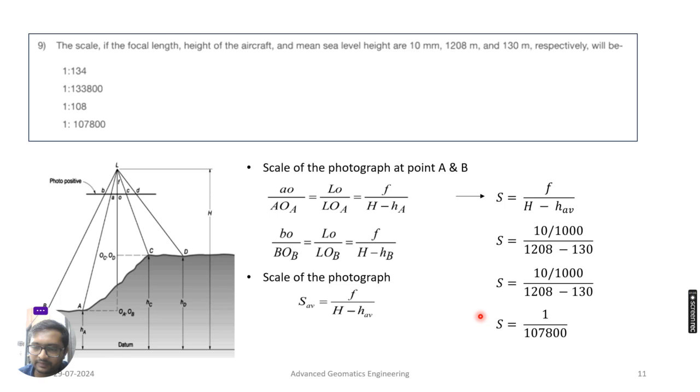So find out the edge. They have not given the scale directly. The value of S is not given, but from the definition we know that scale is a ratio of two distances: distance on map divided by distance on ground. So instead of S, you can write 1:10 or whatever is given to you, that 1 centimeter on map represents 10 kilometer on ground. You have to put both the units in the same manner and find the scale first of all, and then start the question.